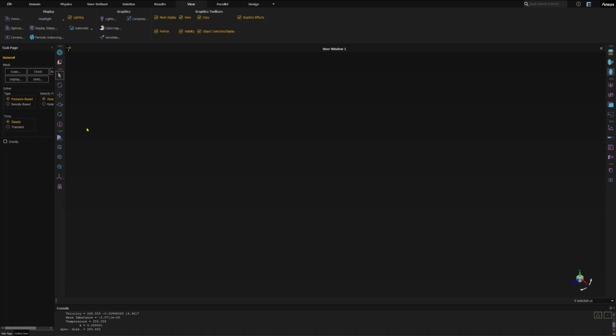Hi everyone, welcome to part 3 of this CFD tutorial series on modeling external compressible flow in Ansys Fluent. In this video, I will go through the post-processing of a transonic turbulent flow around the wing at a 3.06 degree angle of attack and Mach number of 0.8395. I will visualize Mach number contours, identify shock locations, and analyze the pressure coefficient distribution.